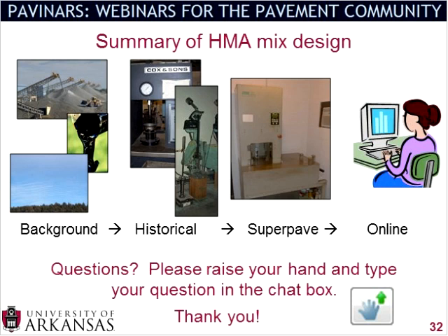That's the mechanistic-empirical portion of it. When we're talking about mix designs, I'm not sure how much you can necessarily use stresses and strains. But I think it would be possible to simulate, say, a Superpave gyratory compactor, a Marshall compactor, or a Hveem compactor, and you might be able to extract some of those stresses and strains, which gets you to the mechanistic side.